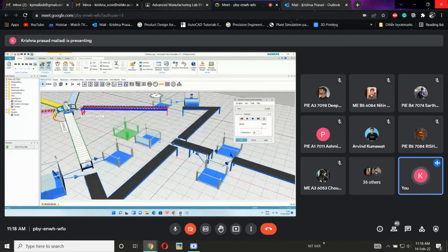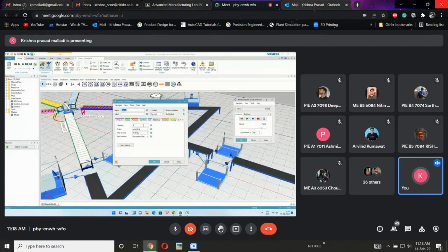Whereas this sorter has conditions, which means we can assign a condition: first in first out or last in first out. I can open this one and increase the capacity just like the buffer. Here, for the order, I need to choose ascending or descending. If I click ascending, it is first in first out. If I click descending, it is last in first out. The time of sort is on entry, so it will sort like this. These are default things, occupation, property, method. So when I click ascending, it means first in first out. If I select descending, it is last in first out. That is the condition it will follow.